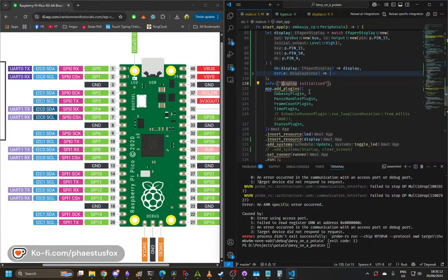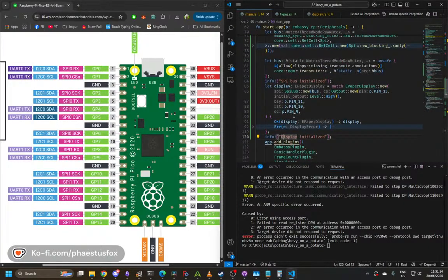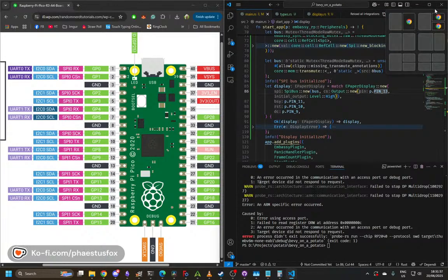God, I've got too many things. Okay, so when I pass in here, I pass in chip select somewhere. So chip select here is an output new high 13. Now the other issue is I could be putting those pins in the wrong mode, but anyway. So chip select is 13, and the 13 is 4 from the bottom. So 1, 2, 3, 4 from the bottom. Okay, so chip select is working.